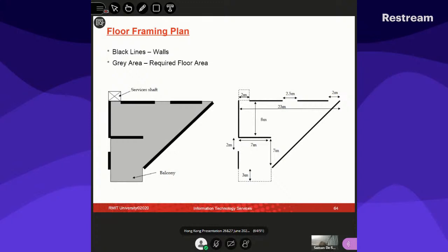Even before you can do the calculations, that is the part you need to be able to frame up, at your level. You are pretty good at rectangular shapes because that is what you have trained on. Now, this particular project provides a little bit of a challenge, because first you have to frame your structure, and know where to put the beam for a start, and how to support your cantilevering edge slabs. That is part of the exercise.